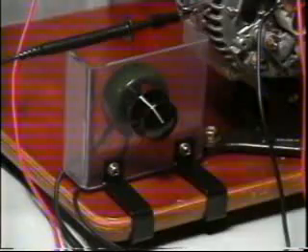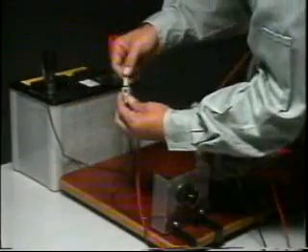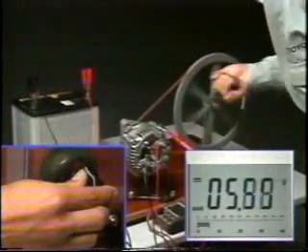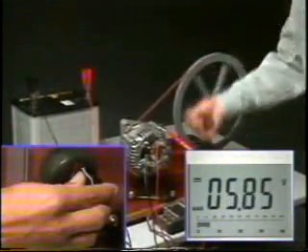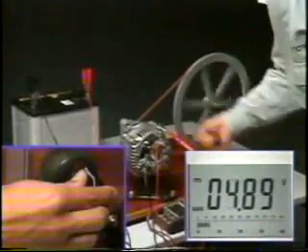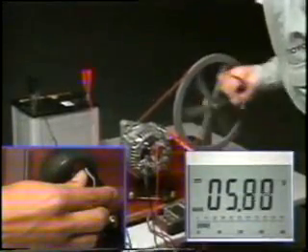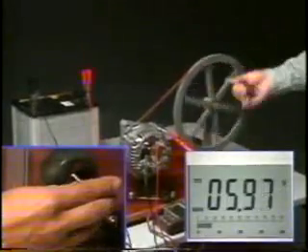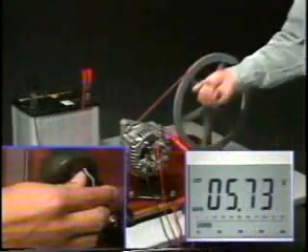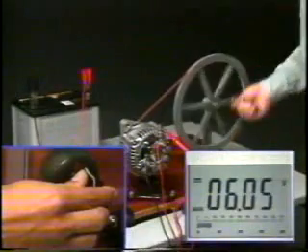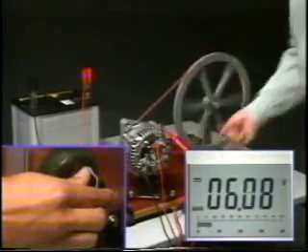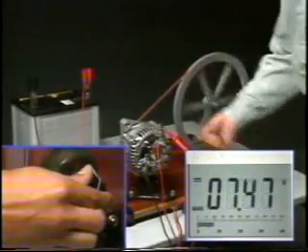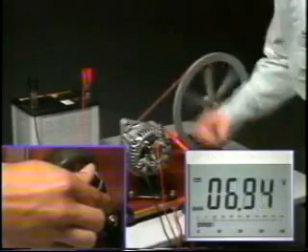We now put a variable resistor between the rotor coil and the battery. When the rotation of the alternator decreases, we can increase the current to the rotor coil by reducing the resistance of the variable resistor. This will strengthen the magnetic field of the rotor. On the other hand, when the rotation of the alternator increases, we can decrease the current to the rotor coil by raising resistance. This weakens the magnetic field of the rotor.